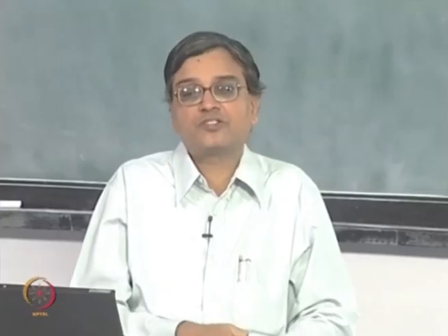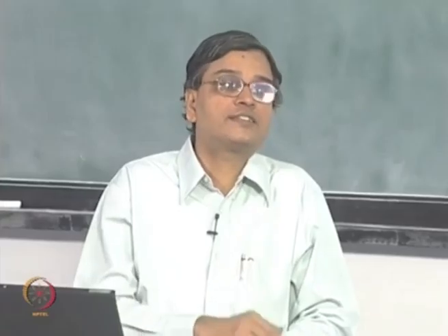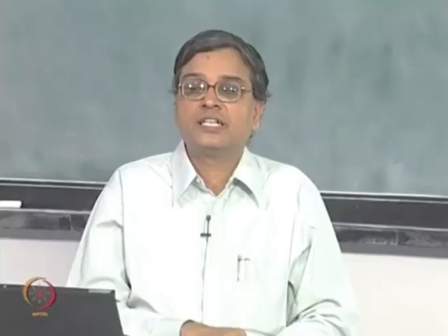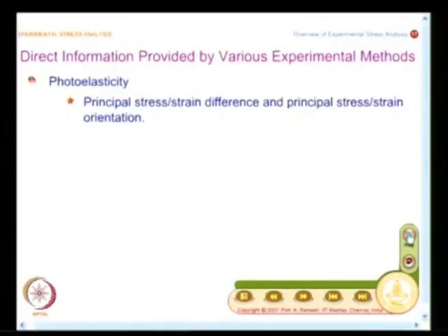And in photoelasticity you get principal stress or strain; because photoelasticity has a transmission approach, you get principal stress difference. If you use a reflection methodology for analyzing prototypes, you can get the principal strain difference, and you can also get the principal stress or strain orientation.